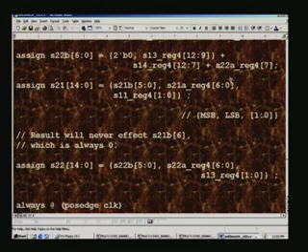So, what we are doing here is we are putting the MSB of the second stage addition and the LSB of this followed here by concatenating, and also not forgetting the last 2 bits which we have not processed earlier. So, this makes up the second stage complete result, and the result will never affect the S21 6th bit, which is always 0, this is what we have already seen. So, just as we had S21, we will have S22 here, and this is precisely the same as what we have seen before for the other 2 outputs of the second stage.